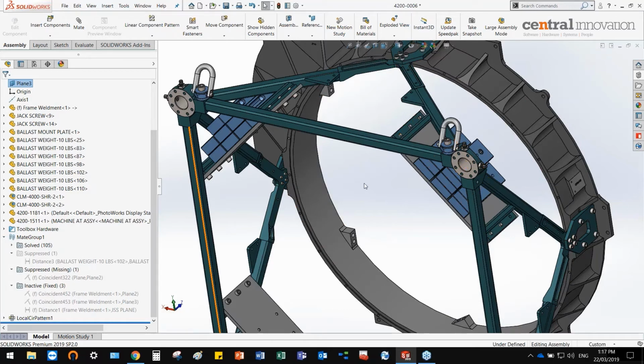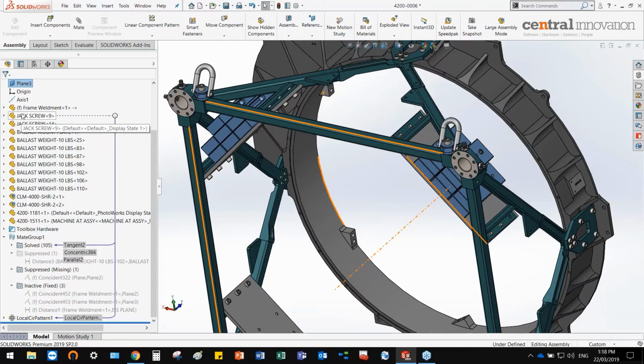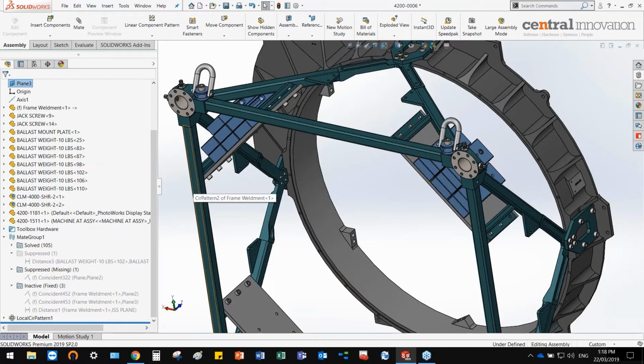Okay, traditionally as well, if you're putting in a lot of bolts or nuts or washers, anything that has no definitive or defined orientation rotationally, it's a good idea to lock the rotation of that part. It ensures that we don't have dashes against the part in our tree, so we can see that it's all fully constrained. It makes it a bit easier to do the rebuilds as well if everything's fully constrained. It's also just a nicer way to model.